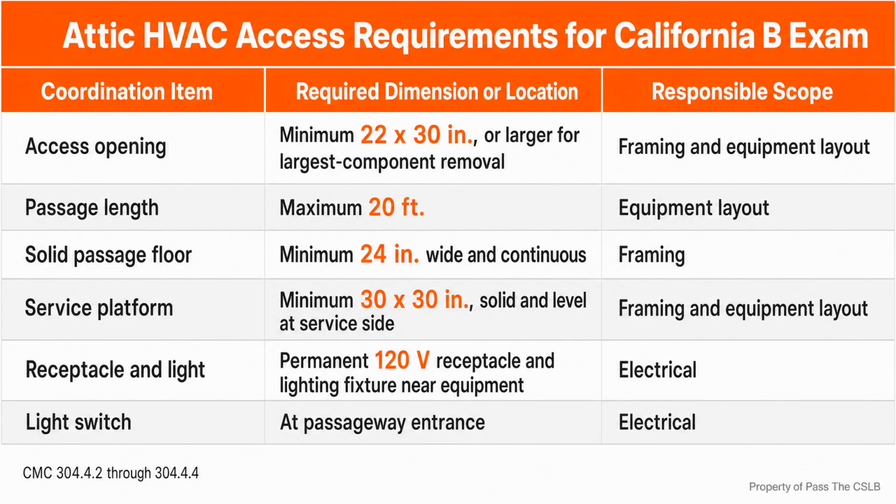Then I inspect the plumbing interface. If the condensate enters a drainage system, I confirm an indirect connection through an air gap or air break. If an air gap is used, I check the required 1-inch vertical separation above the flood level rim. After that, I inspect the secondary protection. I identify the actual method, not a vague promise that the installer will add something later.